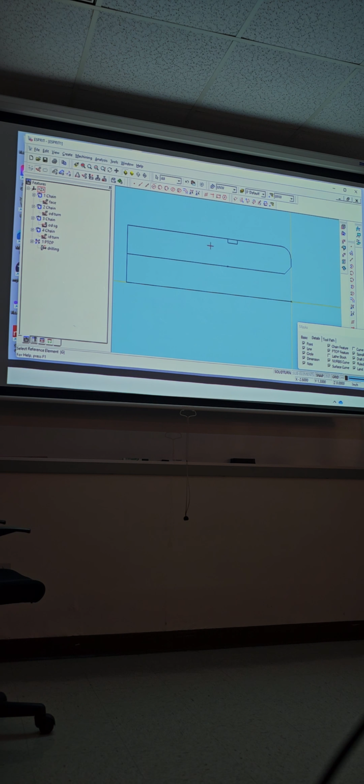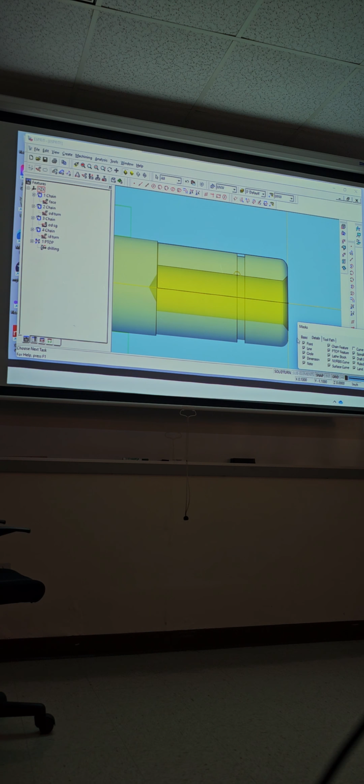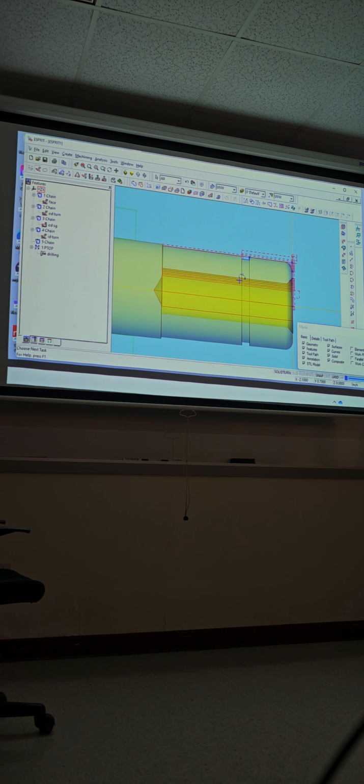So circle, come to that point, and I'm gonna go, what is it, .125, enter. So now we're gonna go to keep that one only. Keep the one you're cutting out. Okay? Now we're gonna select that one, chain, put everything back. Auto chaining. And we have it.